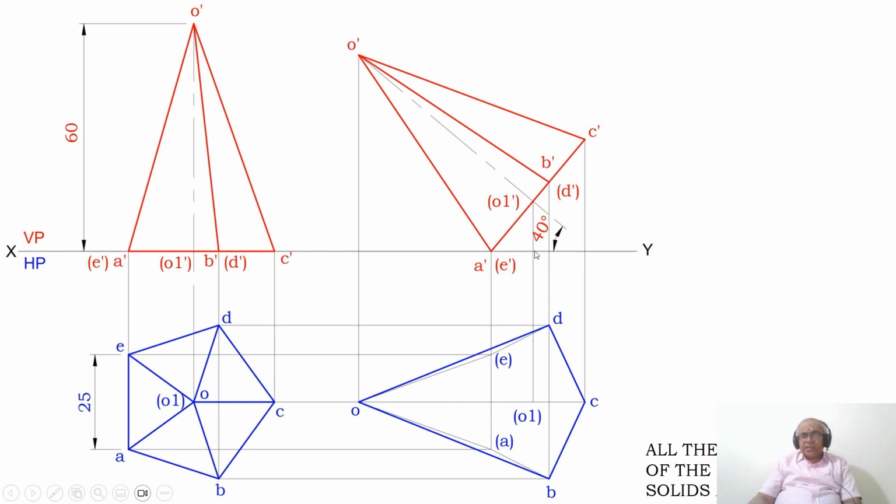Now as we do that, from this axis line you draw a perpendicular to this base by using the compass. With respect to O1 dash, you measure an angle of 90 degrees with respect to the A dash C dash line. Then you draw a perpendicular. Then you measure the distance from O1 dash to O dash by using the compass. From O1 dash, you cut an arc on this and you mark that point as O dash.